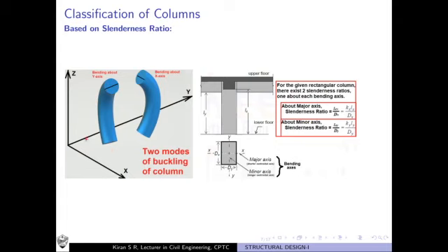Okay, it is with respect to the y that this profile of buckling has occurred. So this bending has occurred with respect to the y-axis. So we say that the first column bends about the x-axis, and this particular column bends about the y-axis. So these are the two ways any column can bend or buckle, about either of the two modes. Based on which we have to define the axis.